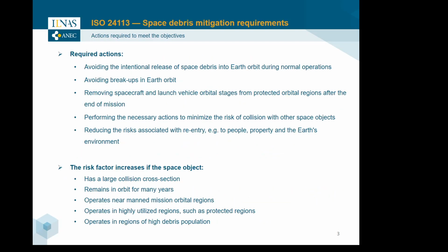So here we have the required actions to meet the objectives set in ISO 24113 and mentioned before. Avoiding the intentional release of space debris into Earth orbit during normal operations, avoiding breakups in Earth orbit, removing spacecraft and launch vehicle orbital stages from protected orbital regions after the end of the mission, performing the necessary actions to minimize the risk of collision with other space objects, and reducing the risk associated with re-entry, for example to people, property, and the Earth's environment. The requirements associated with each of these actions are detailed in ISO 24113.